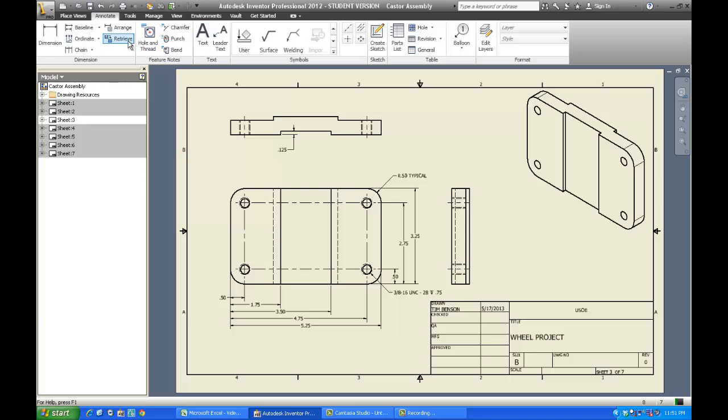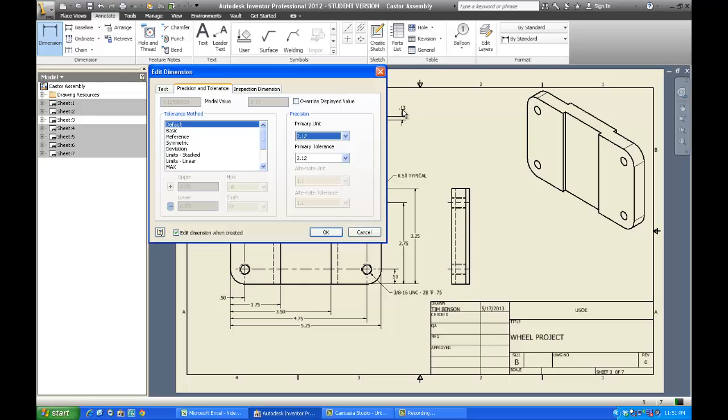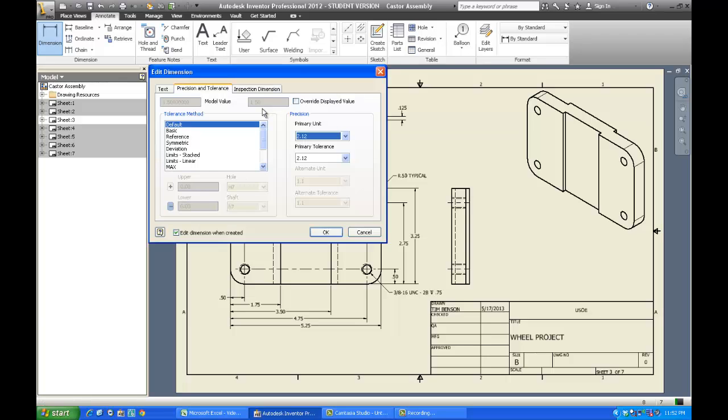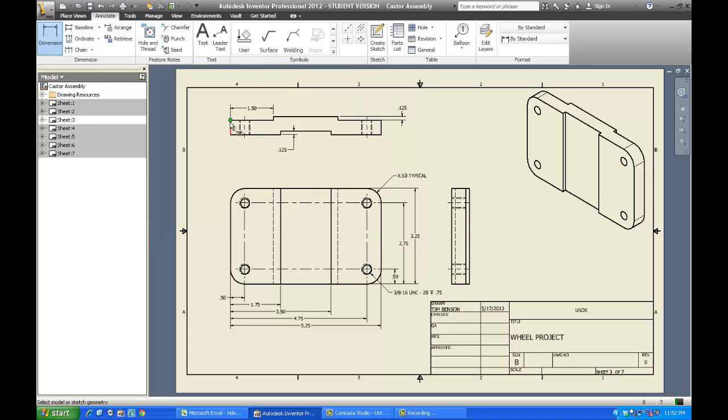Alright, I can do the same thing on the top side. Pull it out here. And again, 3 decimal places. And there she goes. Now, on these parts, what else do I need to do? Well, I actually have to give a dimension that begins right here and measures to that line right there. Create that one. And another one that goes from right here and measures to that line right there.